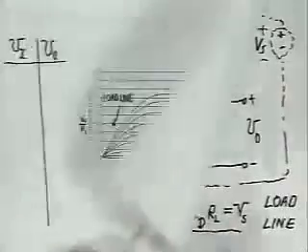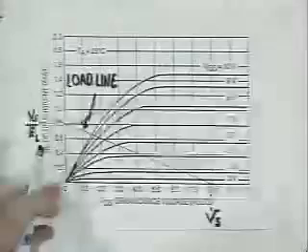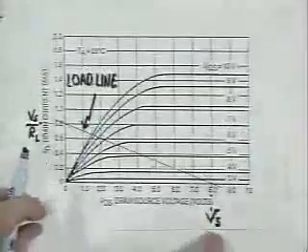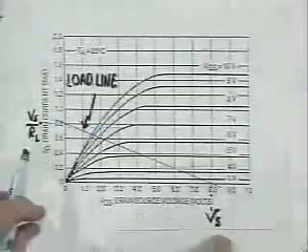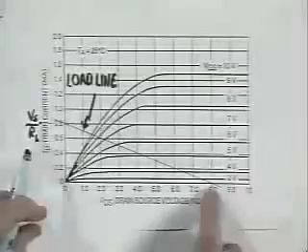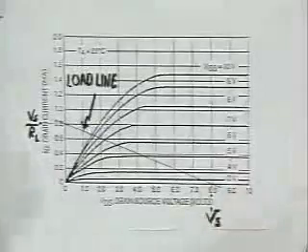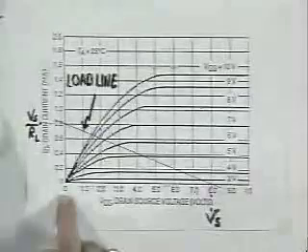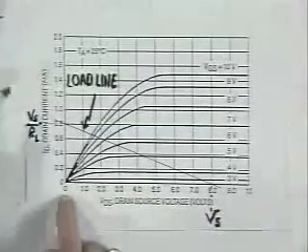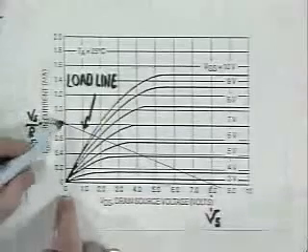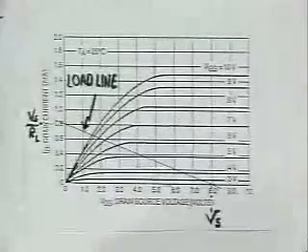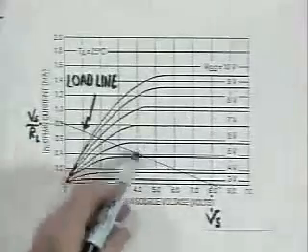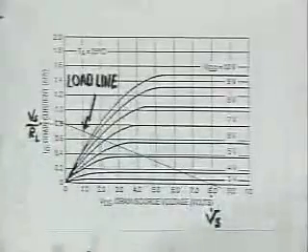So here is that constraint plotted on these characteristics. When I sub D is 0, the circuit constraint says that the output voltage, the drain to source voltage, is just equal to V sub S, and that is that intercept on the characteristics. When VDS equals V sub O is 0, the circuit constraint says that the current is equal to V sub S over R L, and that is that point up on the current axis. Then I've simply drawn a straight line, a linear relationship, the load line relationship between those two intercepts.